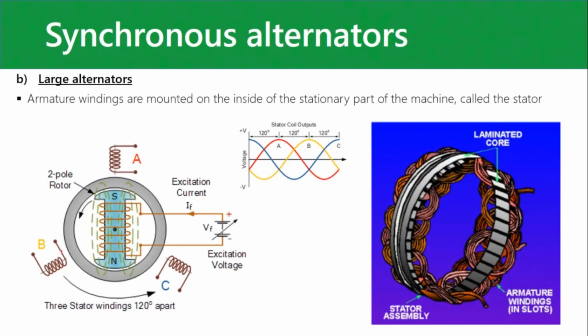So there are two parts to this thing, huh? The stator assembly, or the stator, and this rotor on the inside. Rotor for rotating, stationary means stator. All right, so you have windings on the rotor, and then, using a DC voltage source, you pass this excitation current or field current through that, and then the green dotted lines make a magnetic flux.